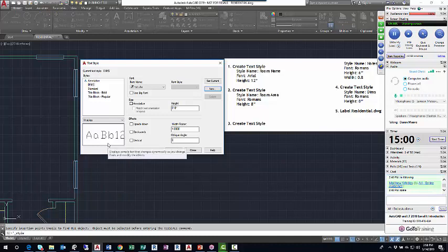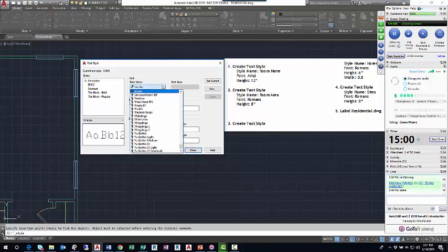It's very sort of square, and I don't know how to describe it. It's terrible. I'm going to use a font called Romanesque or Romans. I'll open up the list and type in ROM as fast as I can, and there's a lot of Roman based styles. Romanesque is the one I'm going to click on.